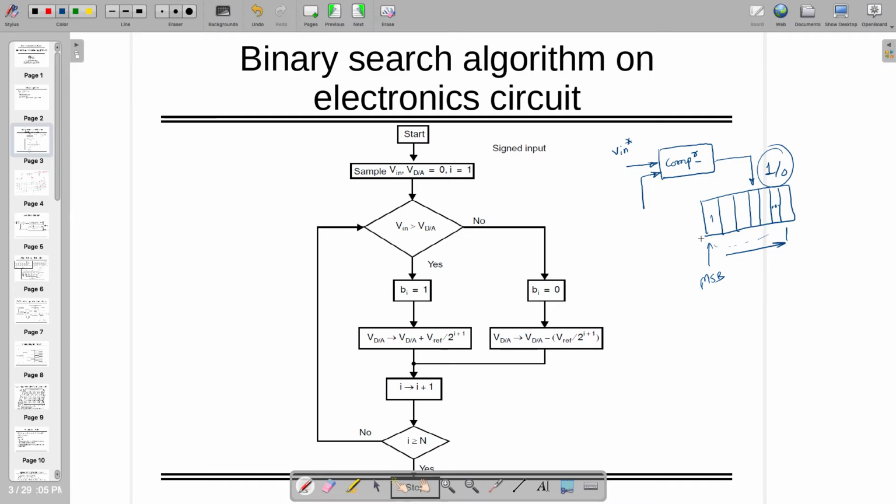So this is what is happening, and when we are doing this, we have to store everything in some capacitors, these bit positions. So these might be each bit, whatever this 1 and 0, from maybe b0 to bn, which are going to convert this digital value again to some analog value, and that analog value will be compared here. We are going to call it VDAC.